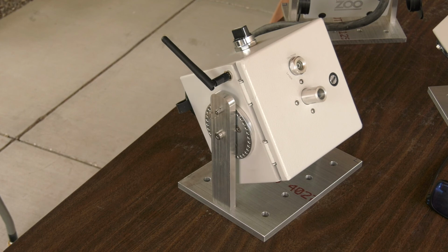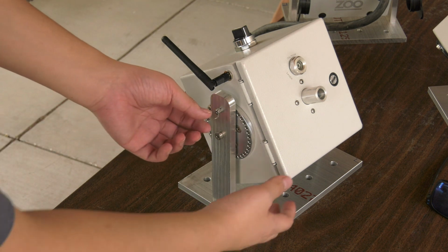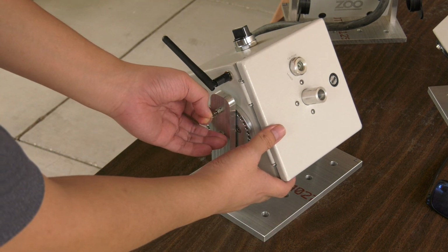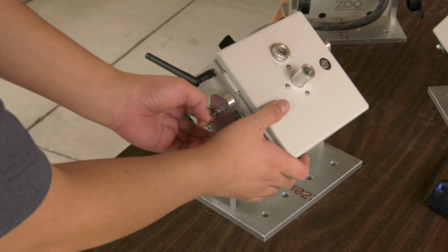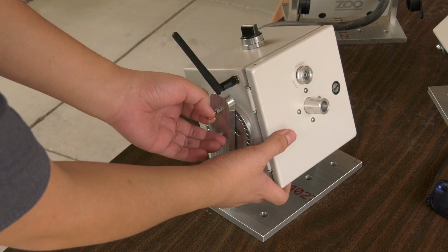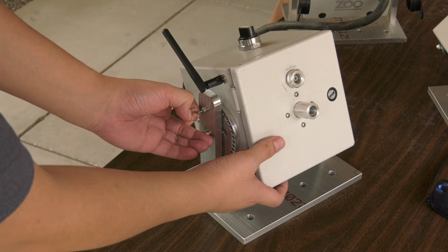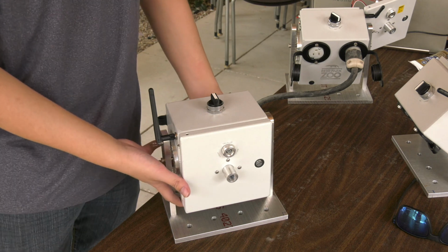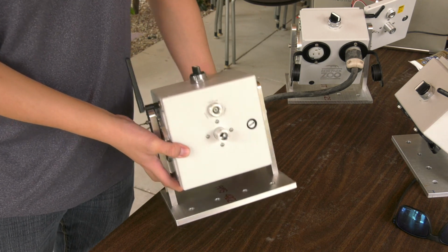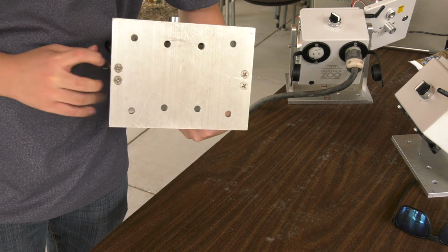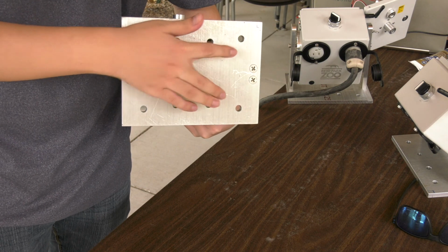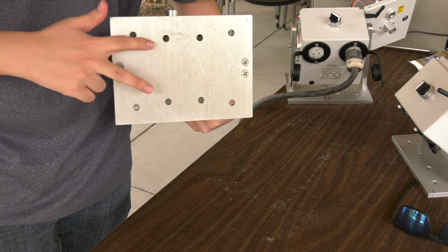Our design includes 2 rotating mounting plates that interface directly and rotate concentrically with the weatherproof case. These plates include holes for an index plunger to lock the angle orientation. The case and 2 plates connect to 2 base arms on either side, which aid in the system's rotation and angle locking capabilities. These arms then screw into the mounting base plate. Various holes on the base plate allow each sensor unit to be mounted to the zoo's current mounting system or to be staked into the ground.